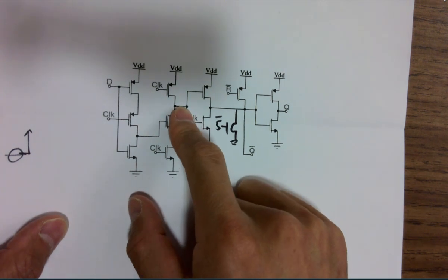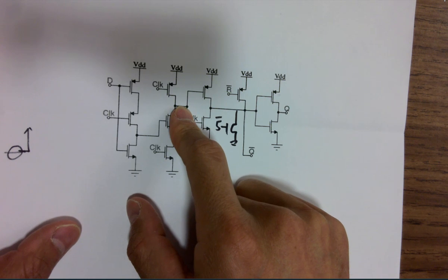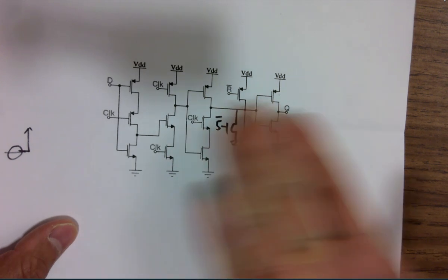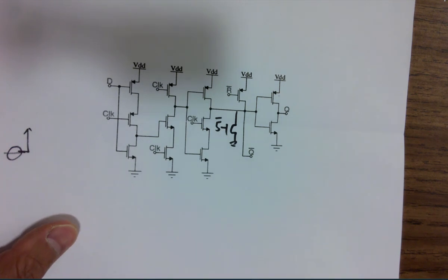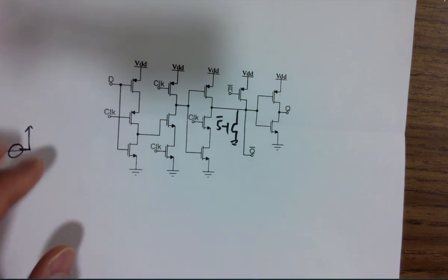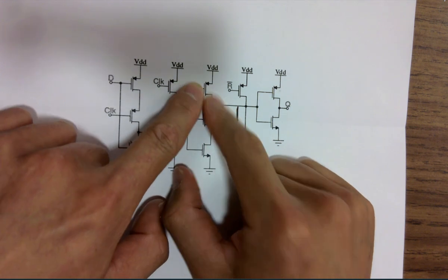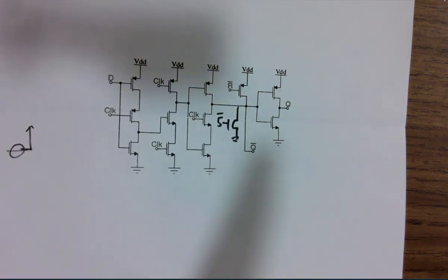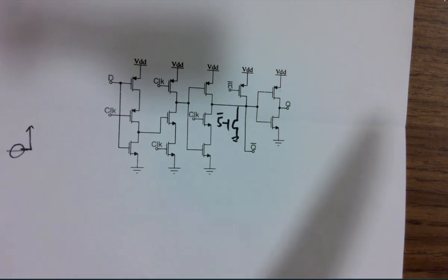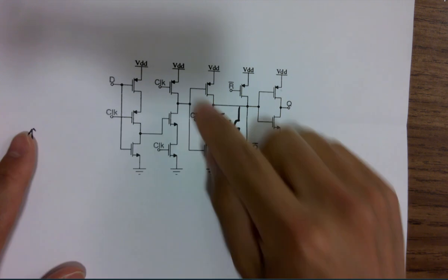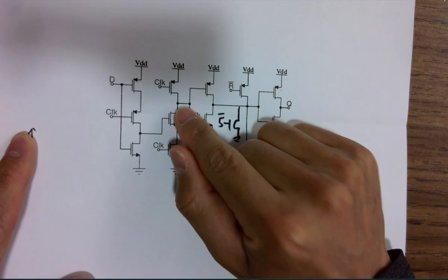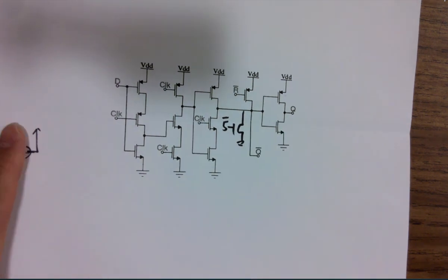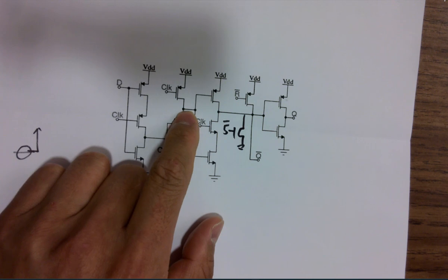So what is able to store charges? What component can store charges? Capacitors, but there's no capacitor. How do you store the charges? It becomes a capacitor. Remember the gate oxide? All the CMOS transistors have the gate and oxide in the middle, and then the channel, right? So all these are forming capacitors. These are pretty small value capacitors, like hundreds of femtofarads. So all these are parasitic capacitors, and a lot of times they cause time delays. But now it's just like a charge storage device. So there will be some charges stored in here.